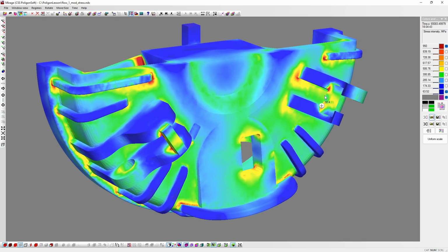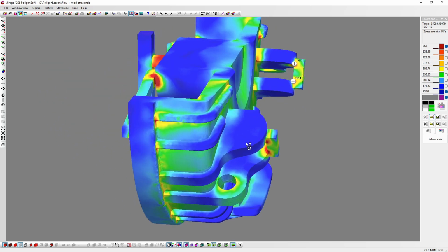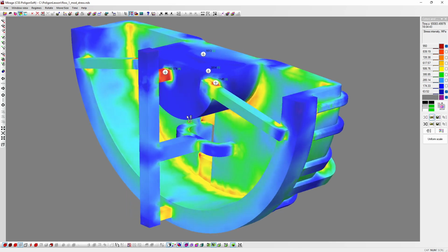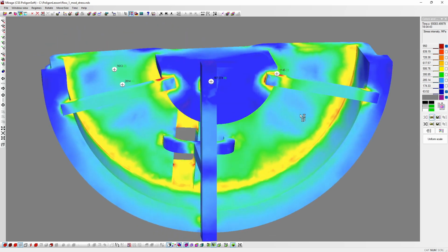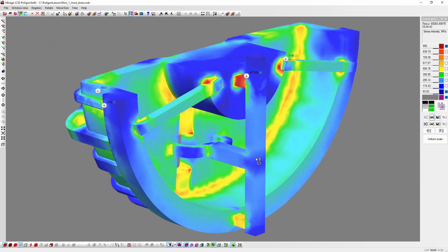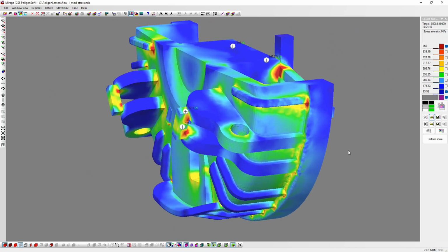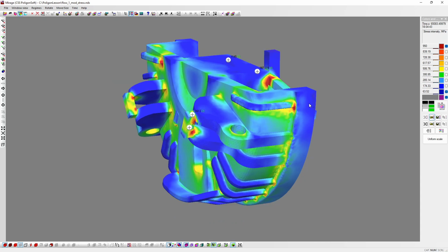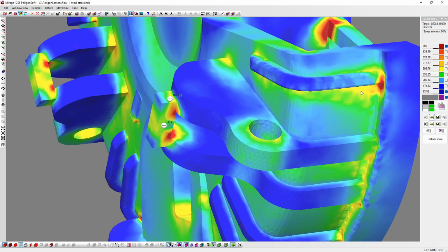In our simulation, we assumed that we have an absolutely rigid mold, but in real life, this is not the case. If critical stresses arise, it is most likely that the sand mold will deform. It is important to remember that large numbers do not always guarantee a fracture, but they are only an indicator of places where problems may arise. To determine the fracture locations with certainty, it is necessary to also simulate the plastic deformations of the mold itself, in addition to establishing the characteristics of the dependence of the tensile strength on temperature. In this beginner's lesson, we will not cover that topic.